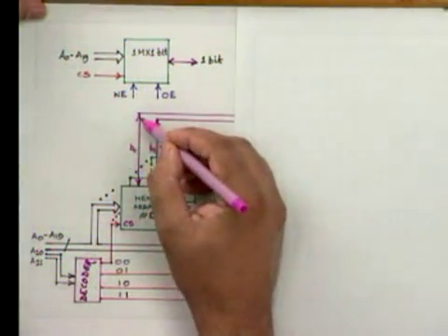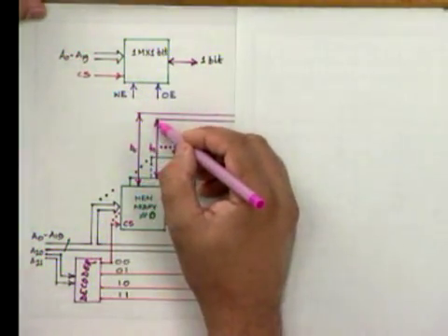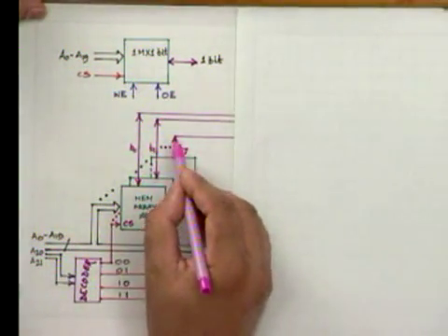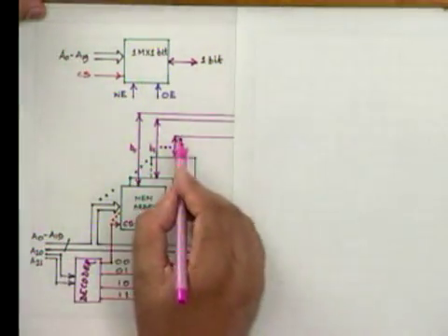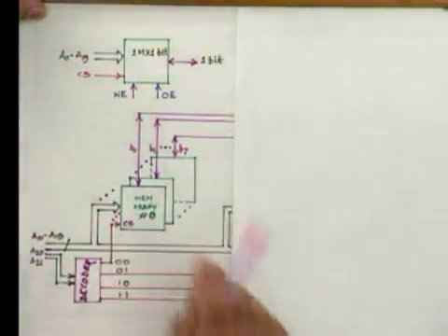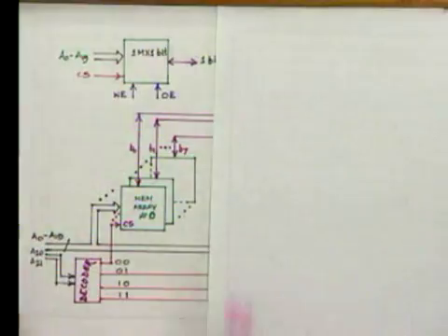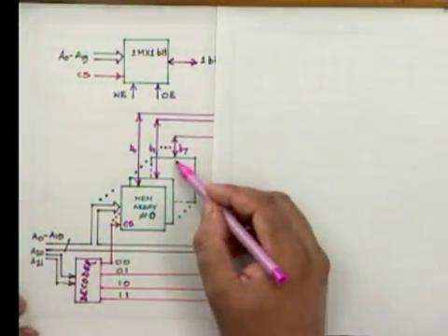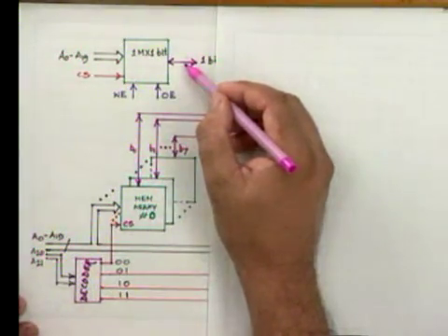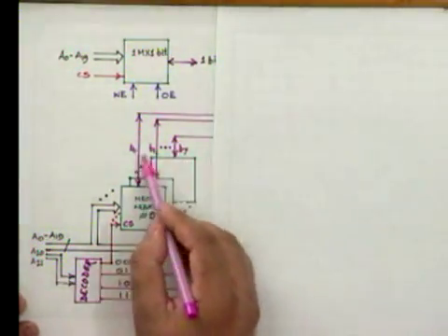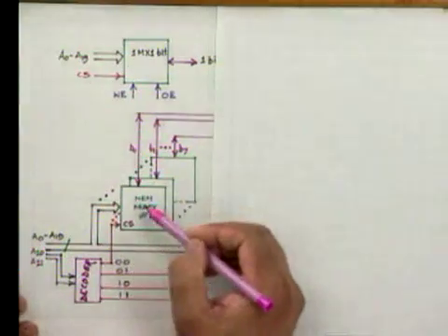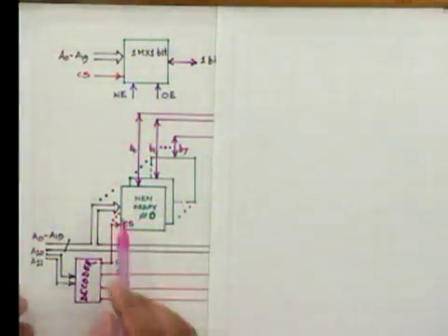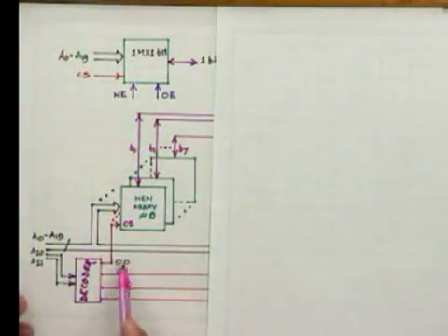The first one will come to B0, the second one will come to B1, and similarly the eighth one will come to B7. This will now go to the data bus. See, this will naturally make 1 megabyte from 1 megabit, okay? The address of this entire stack of memory is A21 A20 = 00.